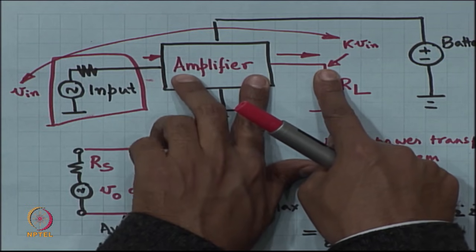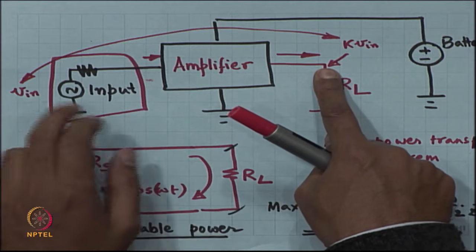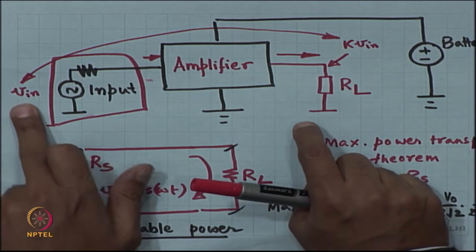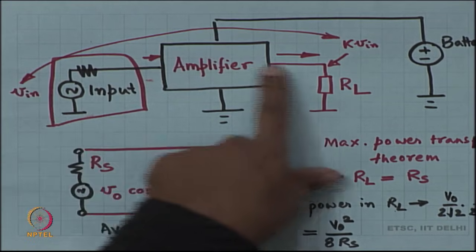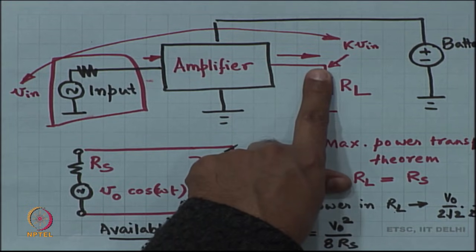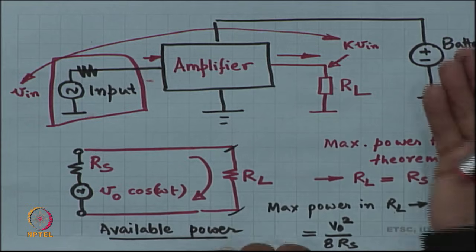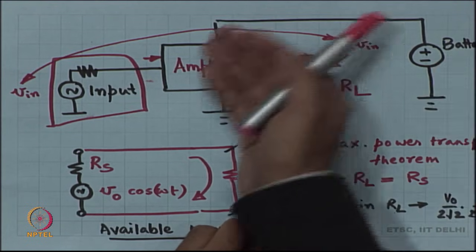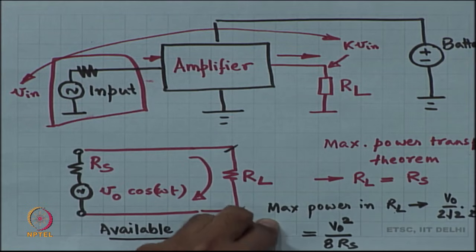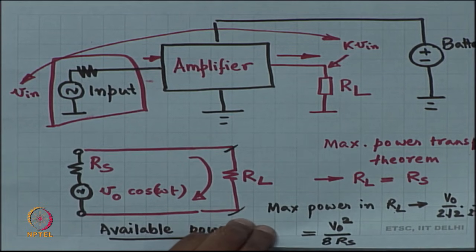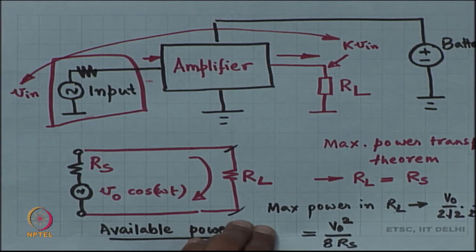We are talking about linear passive elements like L, C and R. As long as the circuit is linear and passive, the input frequency will remain, you will get the same power or less at the output, and whatever power is being produced by the battery will remain at DC. So, think about my answer, rewind, rework this a few times before you convince yourself that this amplifier cannot be made at all using components like L, C and R only.